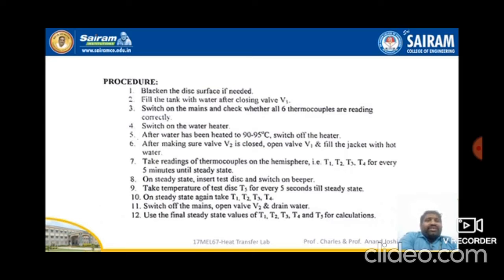Second, fill the tank with water after closing the valve V1, switch on the mains, and check whether all 6 thermocouples are reading correctly or not, as you followed in the previous experiment. Then the fourth step is to switch on the water heater, and we have to wait some time for the water to heat up.